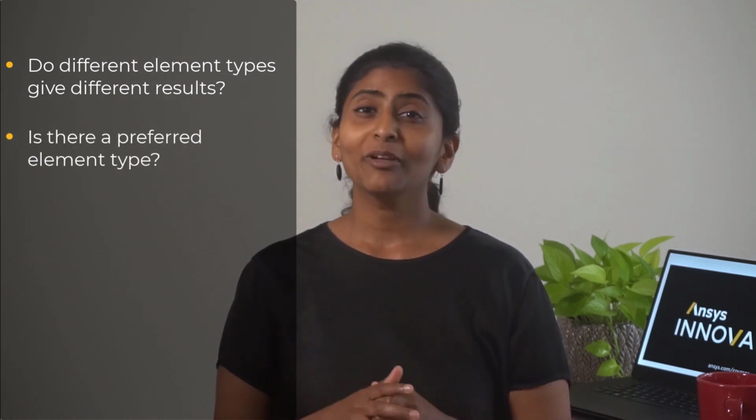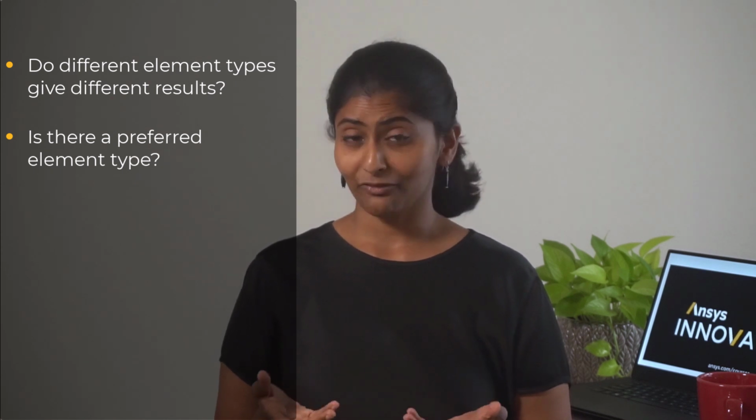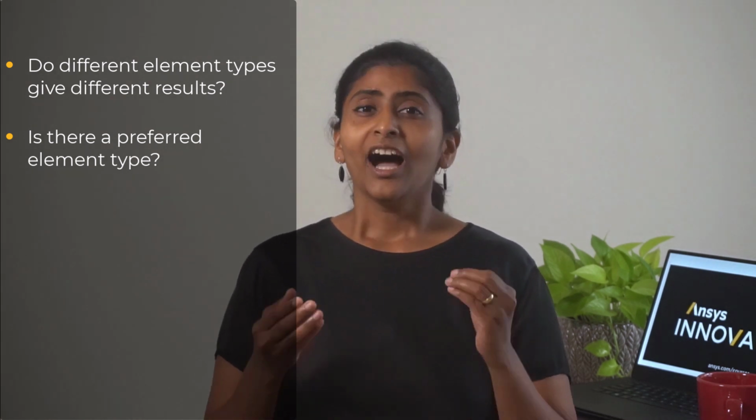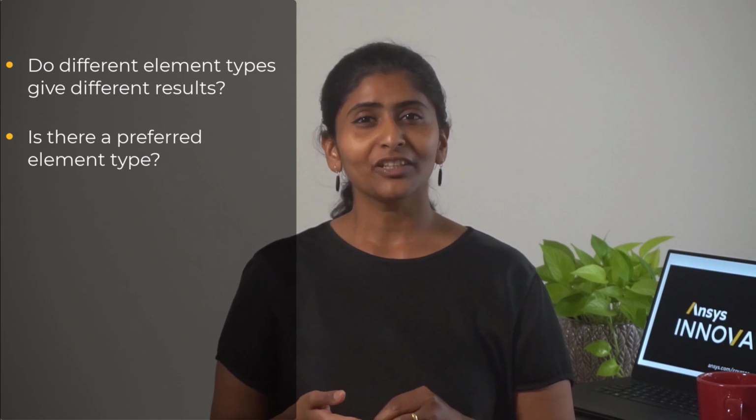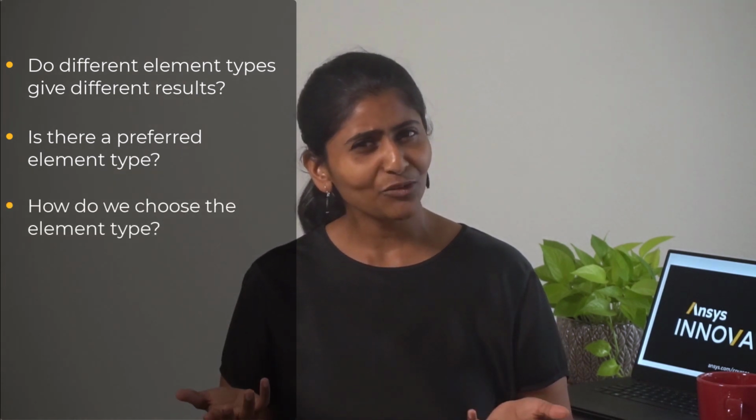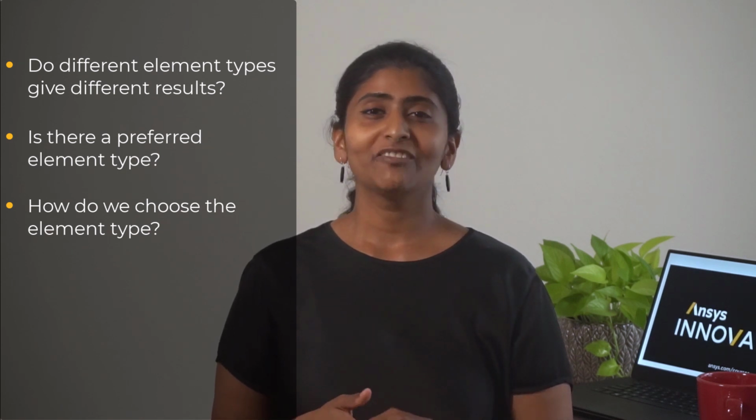In fact, we may also hear from others that in finite element analyses, hexahedral elements are preferred over tetrahedral elements. Is this always true? In this video, we will answer all these questions and clarify the use of different element types for linear structural analyses. Let's get started.